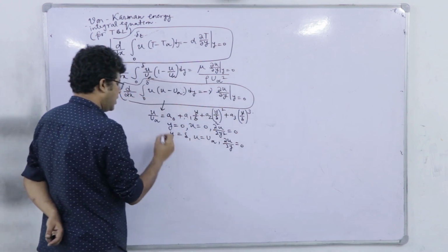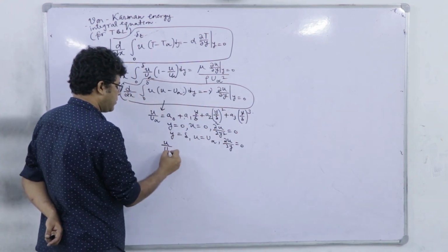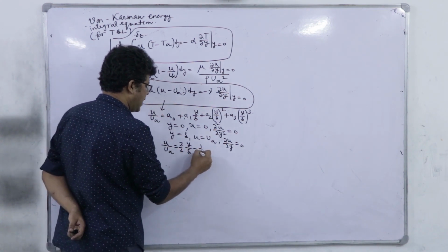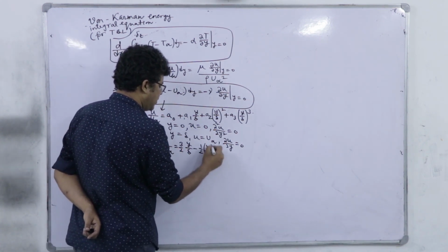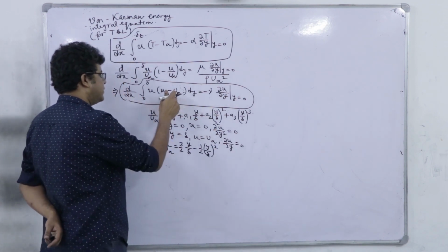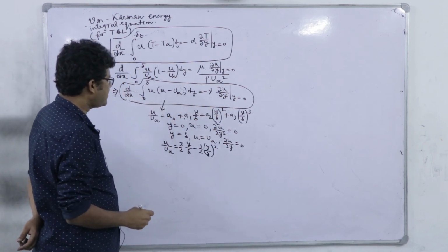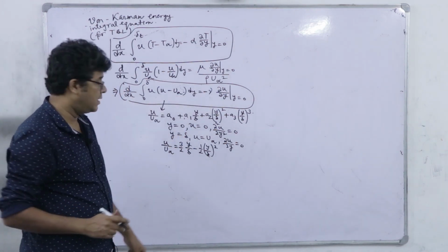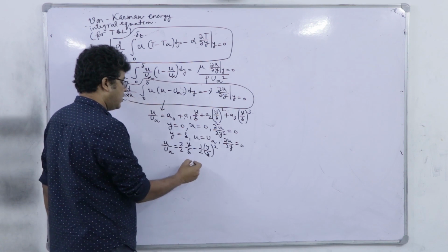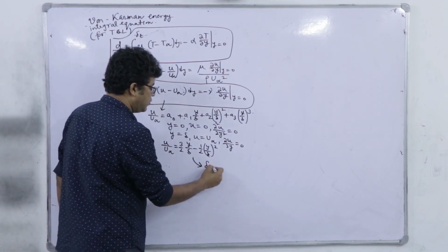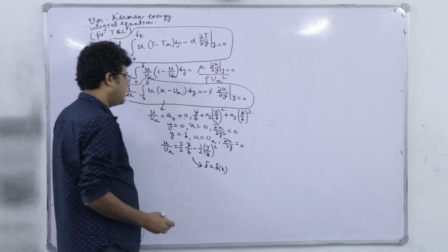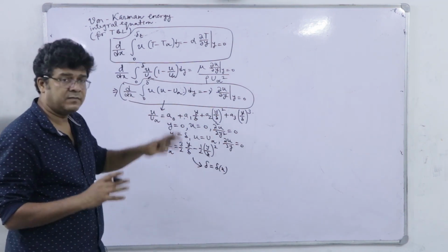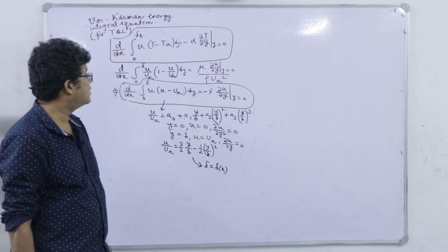So, you have got that solution, small u by capital U infinity as 3 by 2 y by delta minus half y by delta whole cube. We substituted that here and wrote tau w. We finally get a differential equation in delta, which we solved to get delta as a function of x. Once delta as a function of x is obtained, my velocity field is actually solved.